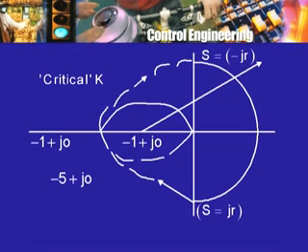In fact, this is only the image of the upper half of the j omega axis. This is not the image of the entire contour. This is an image only of the part of the contour. So, I have to draw the full contour image, which means complete this symmetrically as I have done it, and which also means that what is happening here, how do I join this to this, and therefore, that consideration about the pole at the origin etc.